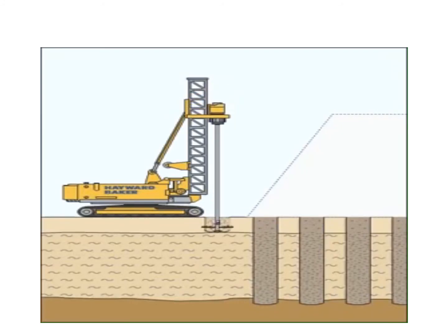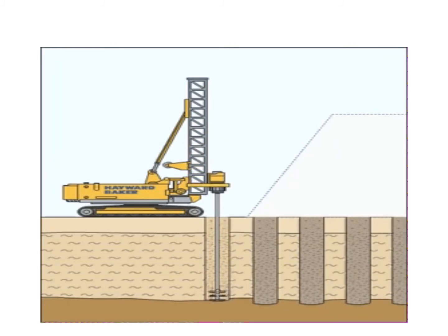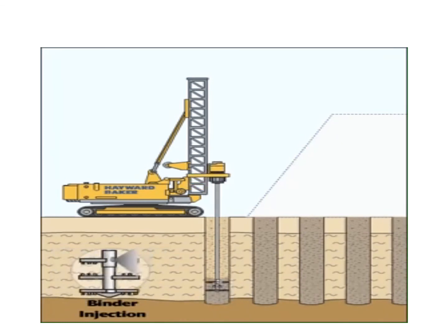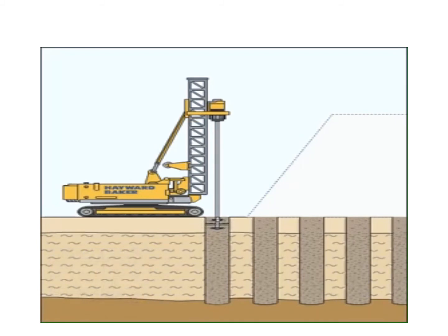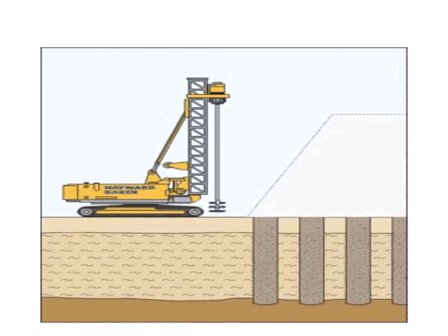See here, this is just like a sand replacement. They are replacing that loose soil with cement, nothing else. Loose soil with cement grouting. Here also, with pressure water is coming out, so that the soil will be replaced by the cement grout, just like sand replacement, nothing else. Then a building may be constructed over there. It will be good for the building.